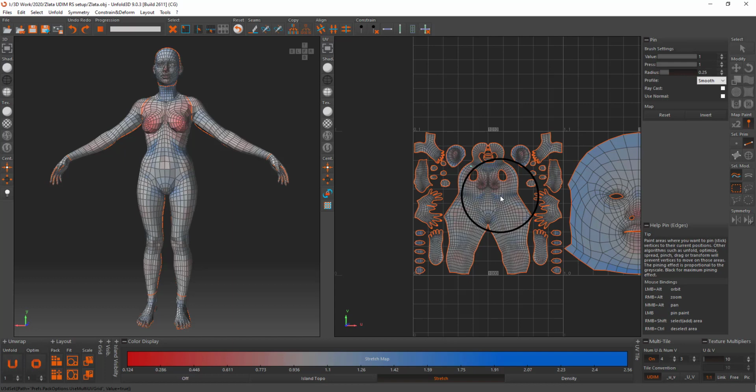Now the downside to this is you're going to be producing many files, much more files than if you didn't use the UDIM feature. As an example, if you wanted to produce a diffuse color map and you had two UDIMs, you would have two textures just for that color map. Imagine that you spread this model across 5 UDIMs. You'll have 5 files just for your diffuse color, 5 files for your displacement, 5 files for your reflection.